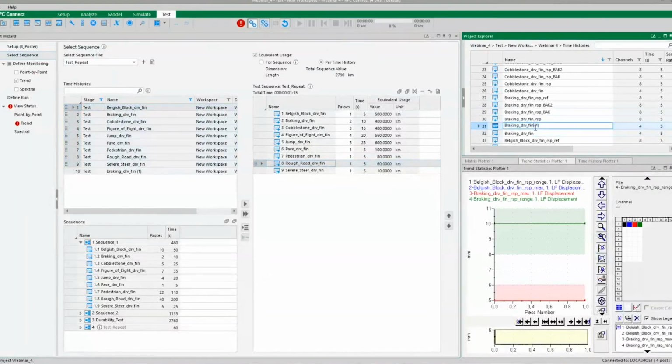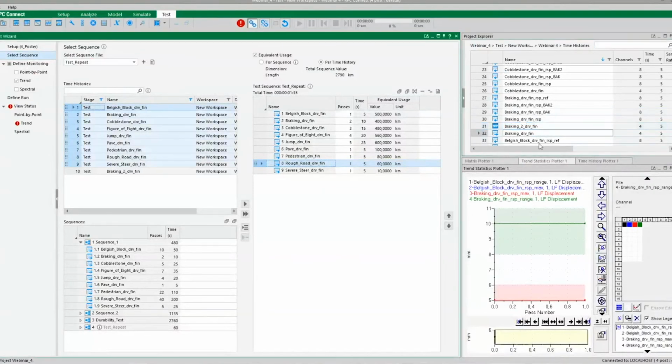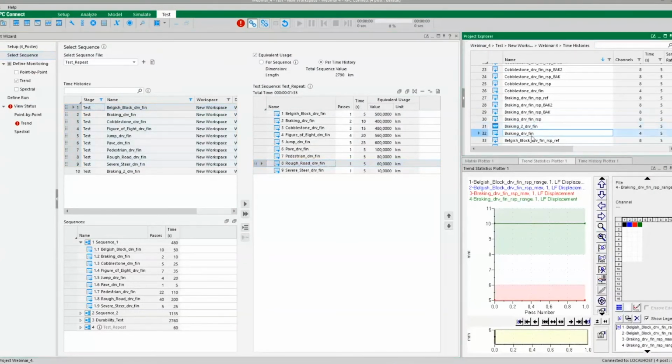So what I'm doing is I'm importing my new file. Just imagine breaking event number 2 is the new file I imported. So let's go for example, and I just want to remap this file. The old breaking drive file 1 should be replaced with breaking drive file number 2. So what you can do is basically click on this remap drive button.